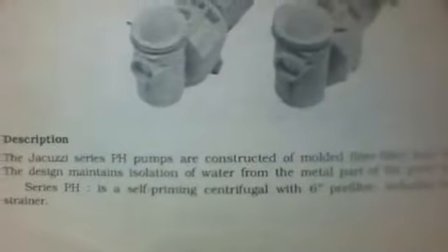There is a description here. Actually, I'll just tell the columns in this. Model number is there, pump, then HP is given, then kilowatt. After that, filter reference is given, then how much sand and gravel, and the filter area. Then filter rate in cubic meters per hour per square meter, pump capacity in cubic meters per hour, and minimum backwash rate in cubic meters per hour. Like that, performance parameters and sand and gravel are given. So we'll go to the description.